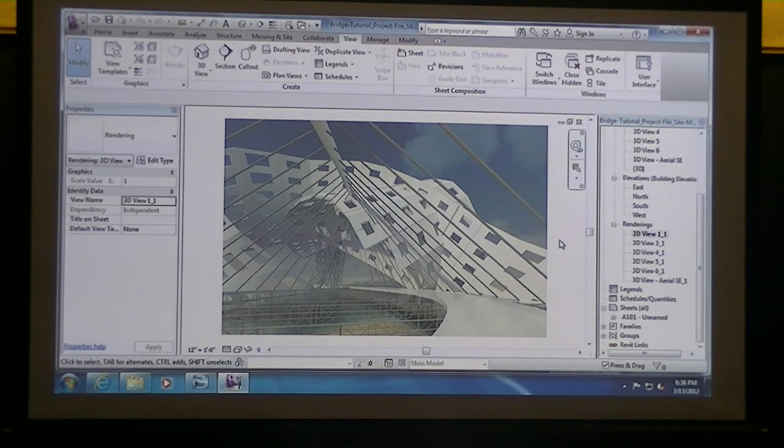And Revit does not have distributed rendering, so unlike V-Ray and 3D Studio Max, where you can link up more than one computer to speed up the rendering time, right now we can only use the one computer and render the image. And so this 1 hour rendering could have taken probably a lot less if they would start to implement distributed rendering into the system.